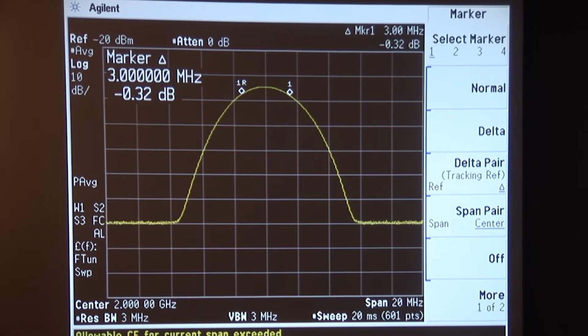Now, people sometimes see this and say, oh, we have a signal that's 3 megahertz wide. We, of course, do not have a signal 3 megahertz wide. We have a carrier wave signal, which, as we discussed in the whiteboard section just before this lab, in the frequency domain would look like a line drawn right here, but we're convolving that line emission in the frequency domain with an IF filter, which is 3 megahertz wide, which is being swept across the frequency range like this, and remember that I drew the effect of that convolution on the whiteboard. We're seeing that convolution here.